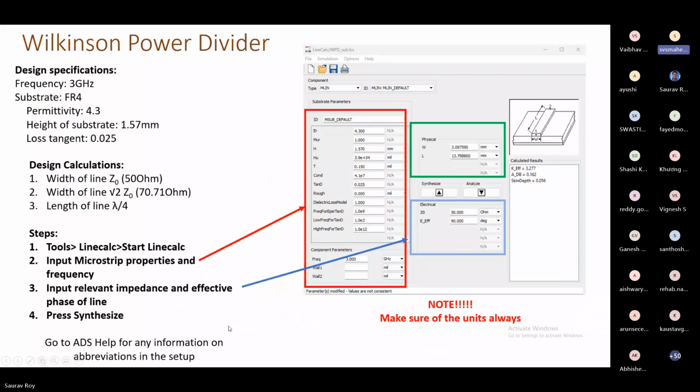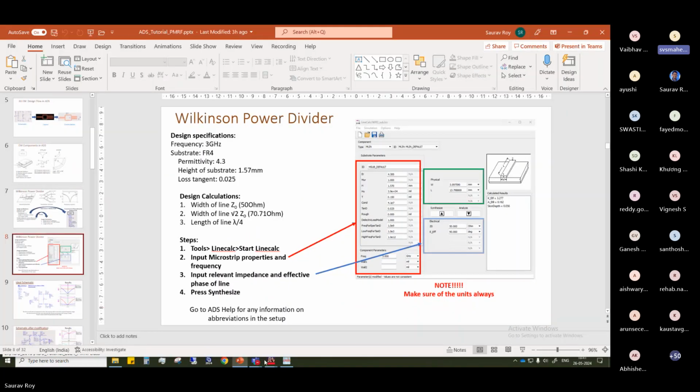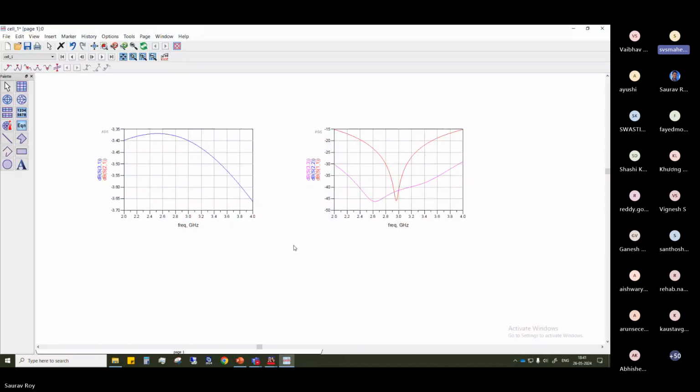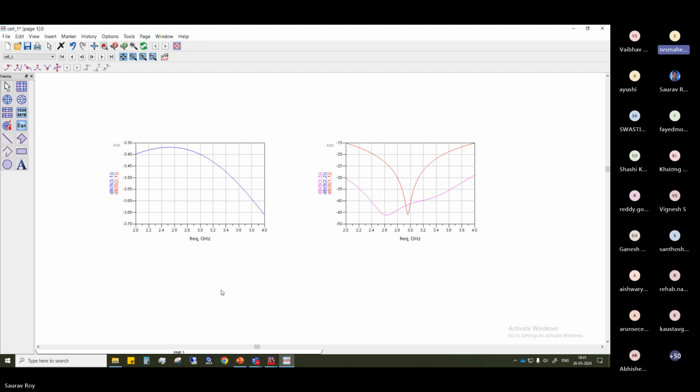So practically, when we implement the circuit, we will get 3.4 or 3.5 generally. This is very good; you won't get this much good. It might go up to 4 dB also. People say 3 dB will be coming, right? That is theoretical. That's why we are doing the simulation, to see what is the difference between theory and practice. Sir, when we purchase these Mini-Circuits parts, it will be like 3.5 only.